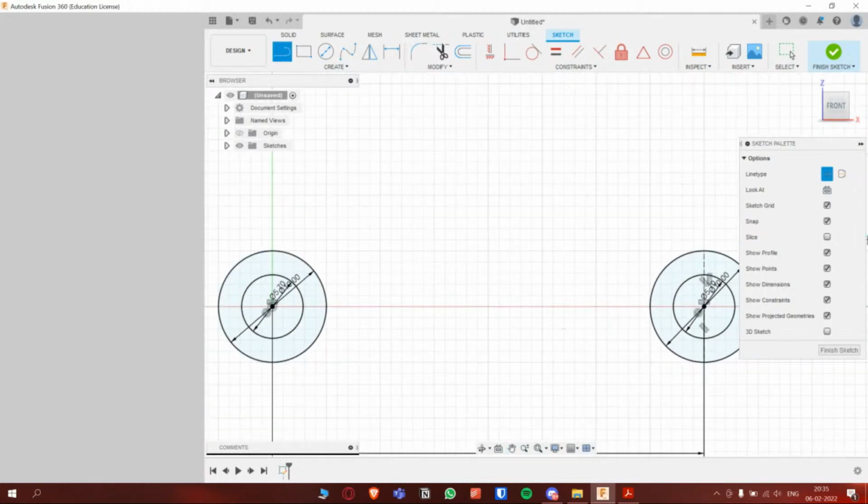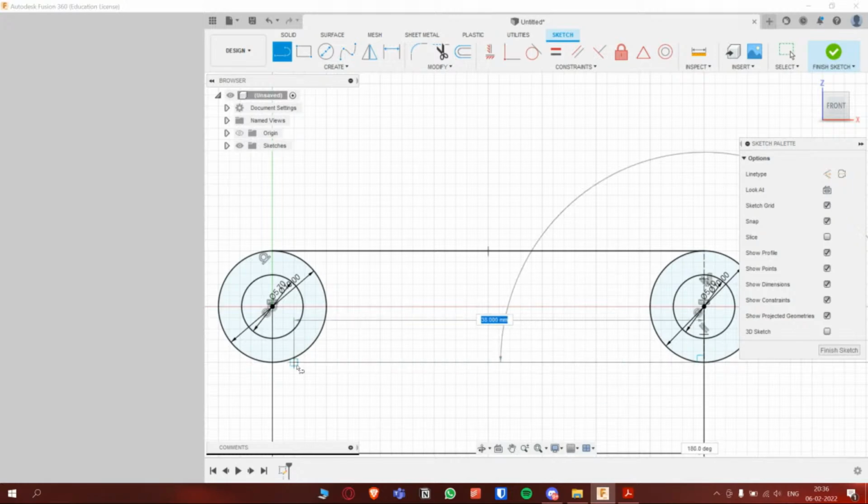Now that both construction lines are connected, we can click off of this construction thing and create the actual lines. Click on the intersection right here and we can see the tangent icon. Make sure you intersect the second circle. Sometimes you might be complacent and connect it over here, but it won't be linked. Make sure it intersects over here. We can see the tangent icon appears on this side of the circle. Click on it and again go to the bottom and complete the whole thing.